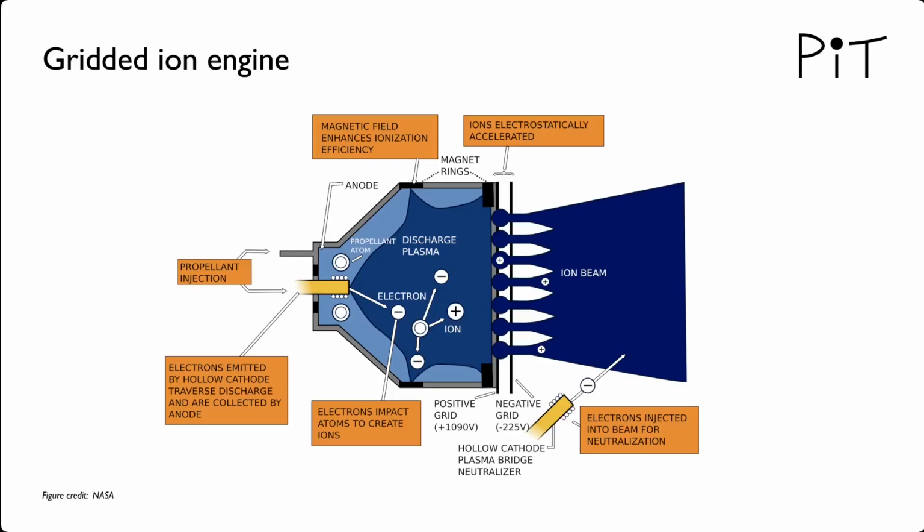The ion beam has a very low density, and to maintain the plasma within the engine, it has to be operated in the near vacuum of space. The mass flow rate from the engine is anyway very low, so ion engines cannot be used to launch a spacecraft from a planet's surface, where a large thrust is required to overcome gravity to even get off the ground. Ion engines are instead used for accelerating once a spacecraft is in space and for maneuvering.